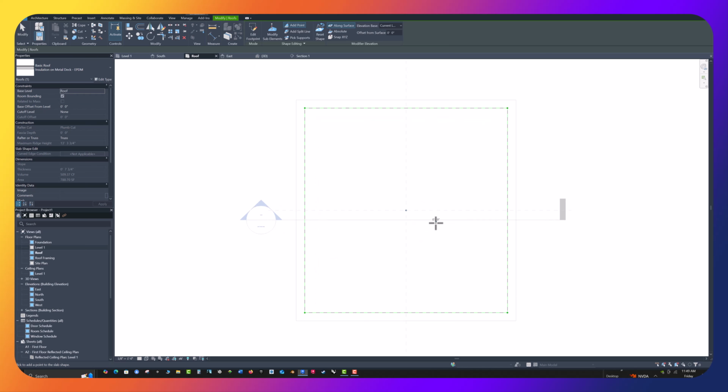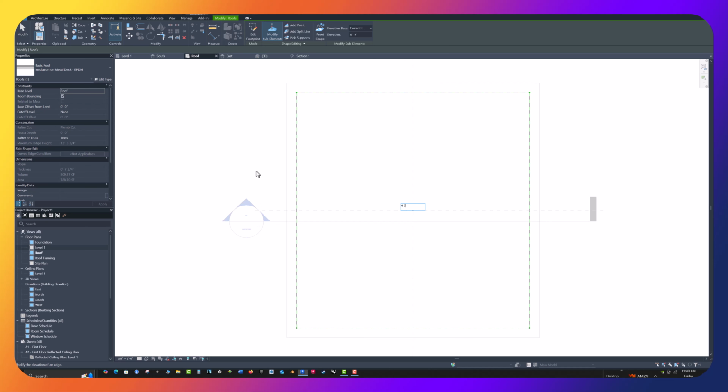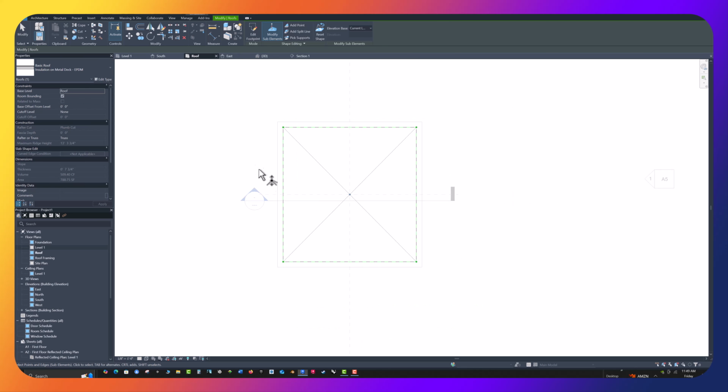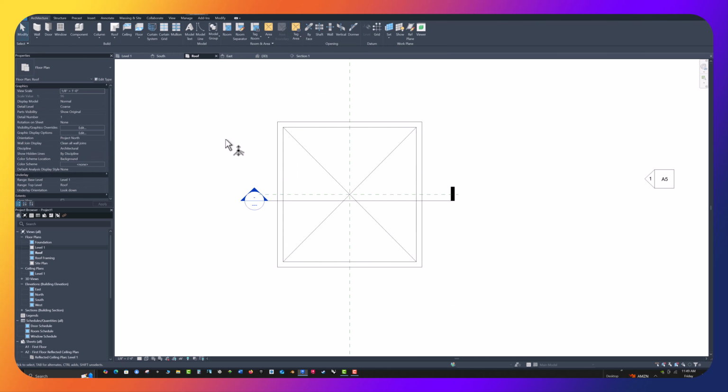and I'm going to select it, and it's at 9 inches. I don't want that. I want that to be, I think it was, 7 inches. Actually, it was 7 3/4, wasn't it? I'm just going to say 0 space 7. So that is to press down. Don't want to press down too much because then you lose insulation. That looks good. So I'm going to hit Escape.